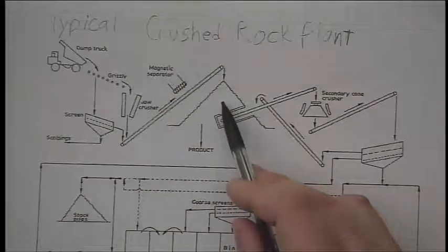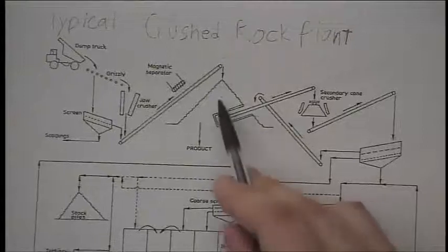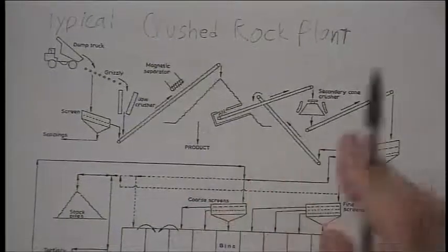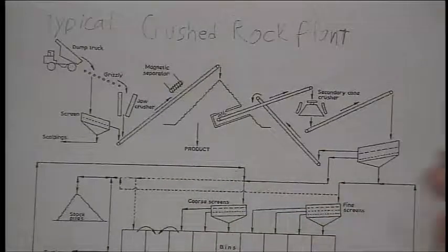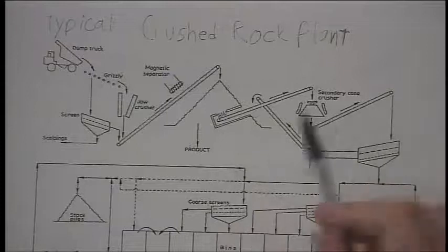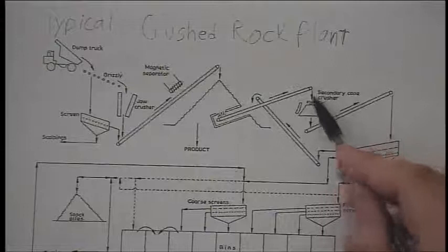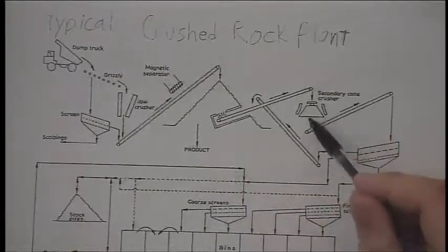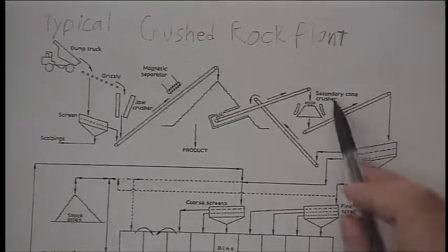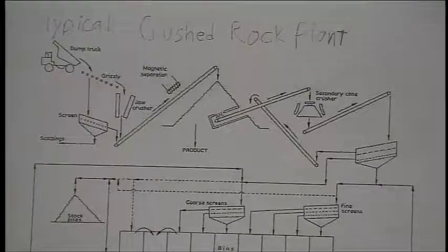and then you'll have a pile that takes it from the conveyor belt. Some of these may be big, some of them not. They may just go straight to a secondary crusher. There are a lot of different steps. This is just a typical flow chart. You may go to a secondary crusher if you didn't like the product that you received. Then you'll do secondary crushing, which a lot of times is with a cone to change the shape so that the shape is nice and cubic.